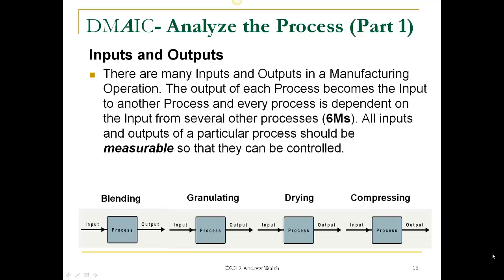All these are inputs into that process, and finally coming out is the granulation on the other side, and some of that may be described by its moisture content and things like that. Those are now inputs into the drying process. So the load of moisture going into the drying process, and that may be a fluid bed dryer or just simple oven dryers. And the output from that would be the finished dried granulation, which now has a certain moisture content. And that now is an input going into the compression area. So varying moisture content in that final granulation has an effect on the process of compression, and that may impact, for instance, the output in terms of hardness and dissolution. So as you see, all the steps along the way have an impact on the final product.